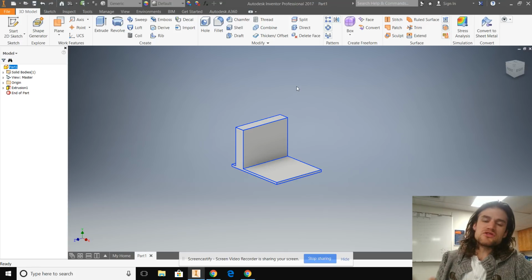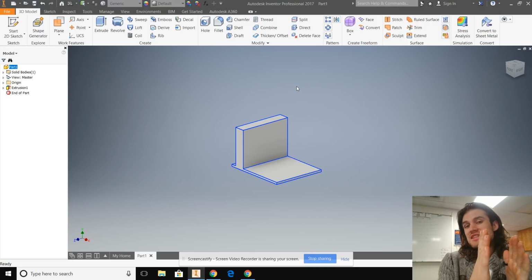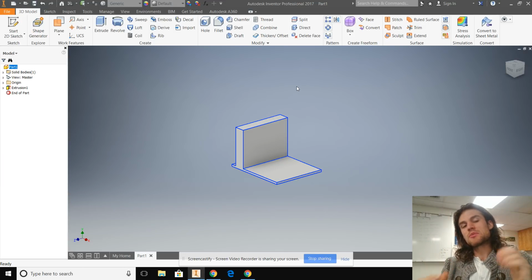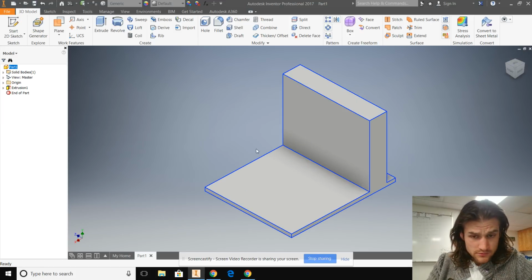As we know, we have two distances, right? The height of the tipping force, and the other distance, which is the distance of the center of weight, the center of mass. How far away is that from the tipping location, the tipping point? So let's take a look at how we might glean some insights right here as to where that center of mass is. It's actually going to help us be more precise too.